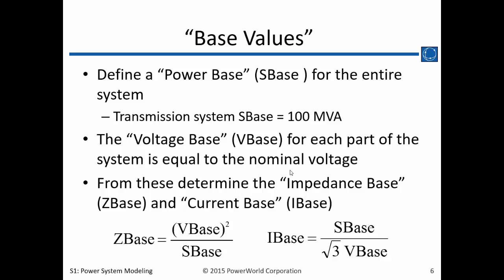And the power company in Hawaii bought our software, and all of their values were off by at least a factor of 10 because they used an MVA of 10 and we used 100. So we modified the software so that they could set the system base to 10 MVA, and it would use that system base for everything, and then their models matched up.